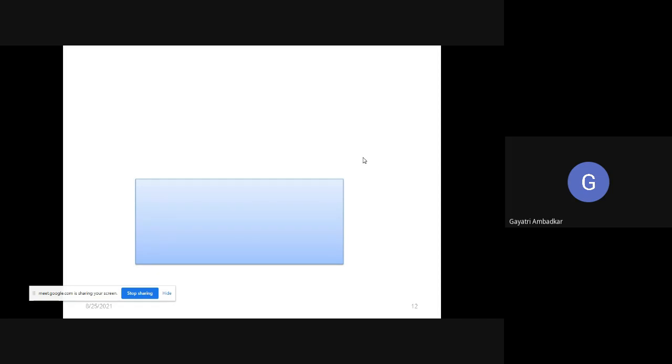Okay. So MOSFET construction, we have seen, we are learning N-channel enhancement MOSFET. Okay, N-channel enhancement only MOSFET. So if you see the construction of this MOSFET, that there is a substrate. Initially, there is a substrate or the body which is doped with P-type semiconductor.